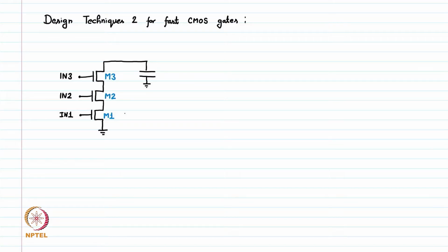As we discussed earlier, whenever two terminals are joined together using a wire, that creates an additional node in the circuit, and these additional nodes will have some parasitic capacitance as well. So in this circuit, if we see carefully, we have two additional parasitic capacitances which we are drawing in green color. We have an additional capacitance here, let's call it C1, and one more additional capacitor here, let's call it C2.